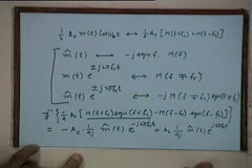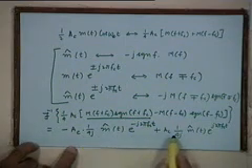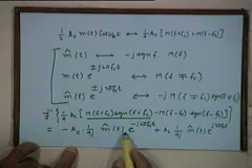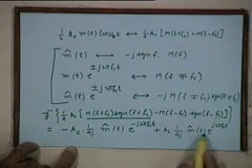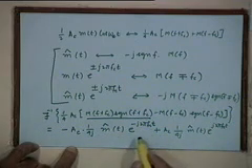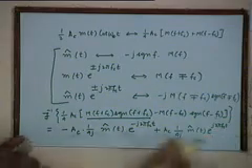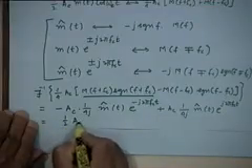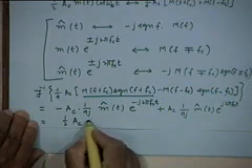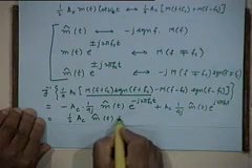Are you all with me? So now if I combine these two terms, what do you get? Take m hat t outside as a common factor, you are left with e to the power j2 pi f ct minus e to the power minus j2 pi f ct divided by 2j, right? So this is nothing but, let me raise it slightly so that you can see it properly, half of A sub c, what will it be equal to? M hat t into sine 2 pi f ct.